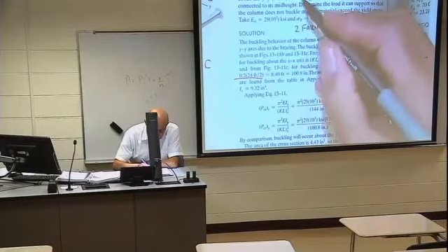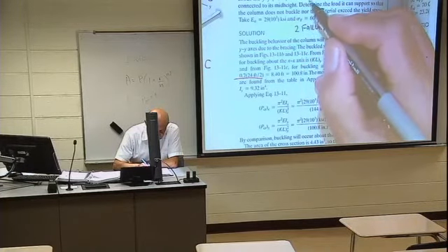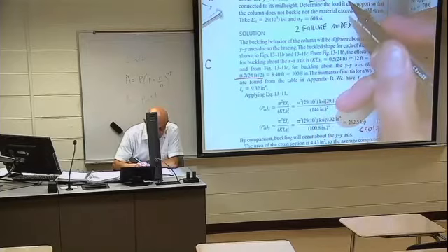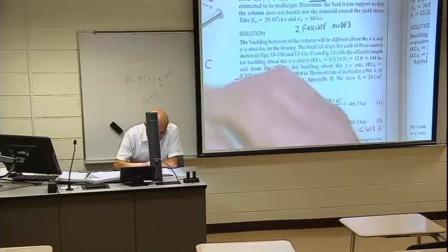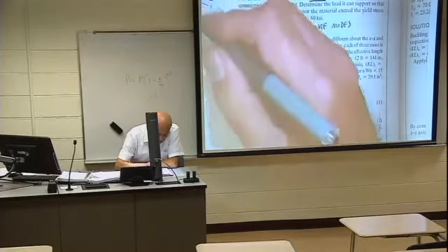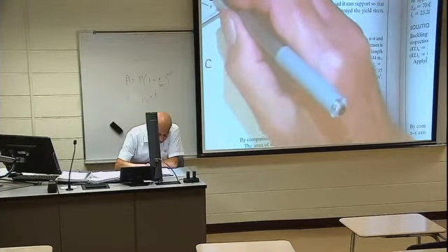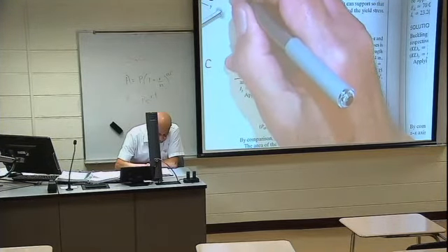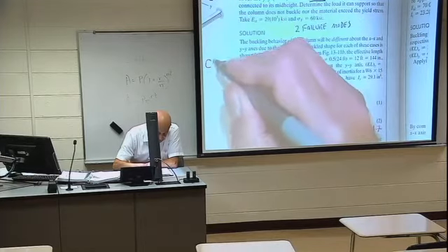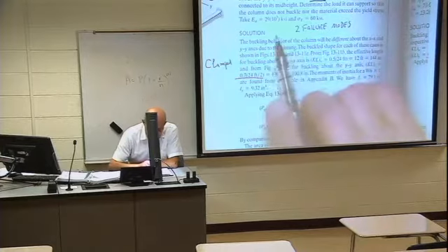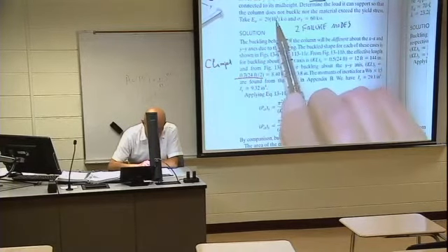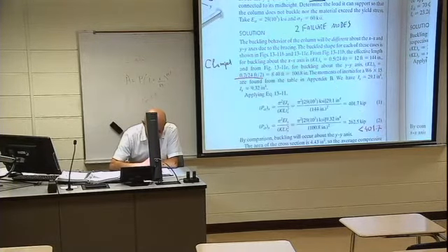So how do we do the bracing? We are using some struts that are assumed to be pin connected. So these are pin connected. So this is clamped, and this is also clamped. Here there is simple support.